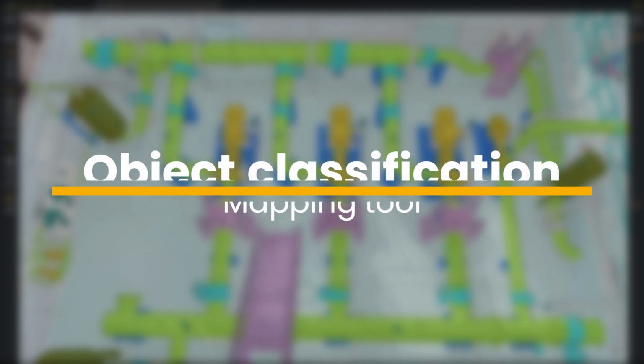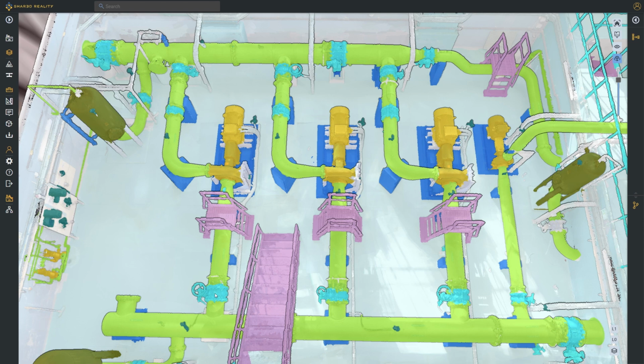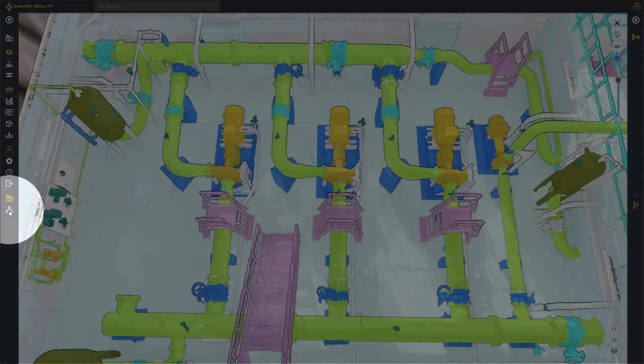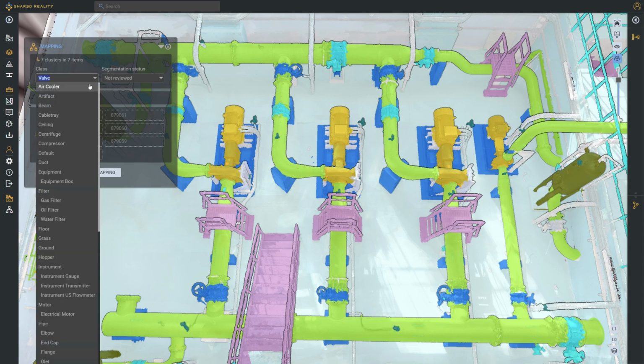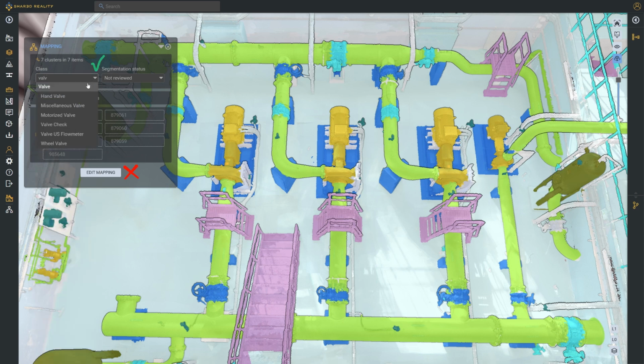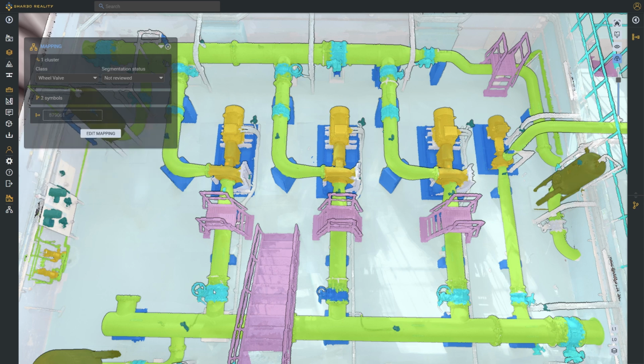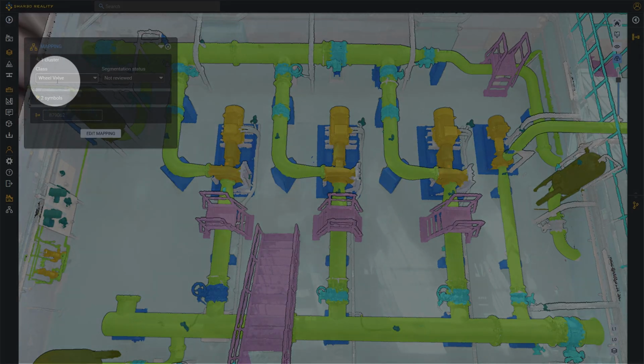Finally, the mapping tool, as you may have seen, also allows you to modify the class of the 3D object that is selected. Now, we can go even further and modify multiple objects class at a time. To do so, first, multi-select them using the Control key on your keyboard and then open the mapping tool. Attention, change the class without clicking on Edit Mapping. If you click on it, it will merge all my currently selected valves into one 3D object. After choosing the right class for my selected valves, they all individually became low valves as expected.